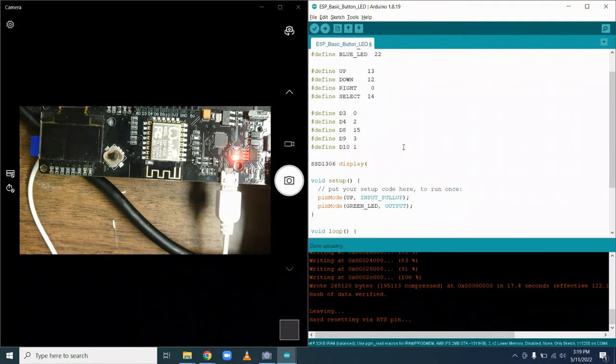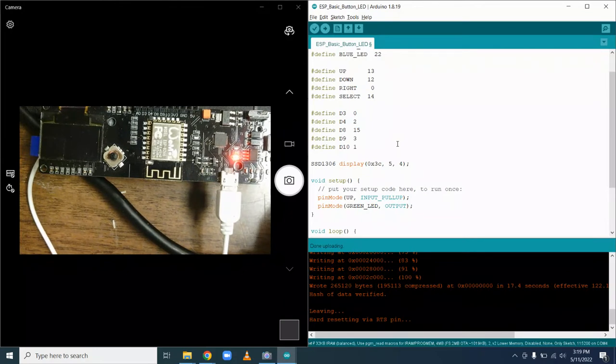To create it this way, we need to pass it the location and what its address is in the pins. The address is 0x3C, which is a hex address for the I2C protocol. Doesn't really matter. Get these magic numbers, and we should have access to it. I'm going to go look at my code further down because I am not smart enough to remember all this stuff.